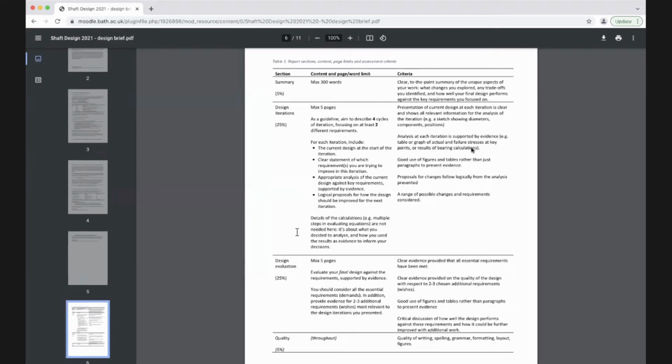But if the torques are fairly small, then that means that in reality, you're not going to have a key that's only 2 millimeters long, because that would be really fiddly and it would probably slip round if it was under stress, and you wouldn't do that. That's why there's this guideline that it should be at least twice the width. That's just a guideline. In reality, if you've got a sprocket that's this width, then there's no real harm in having a key that's pretty much the whole width of the sprocket from end to end. And then you do the calculations to check that that's big enough. And if the length you find is much smaller than that, then the answer is yes, it's big enough. So you just go with that.